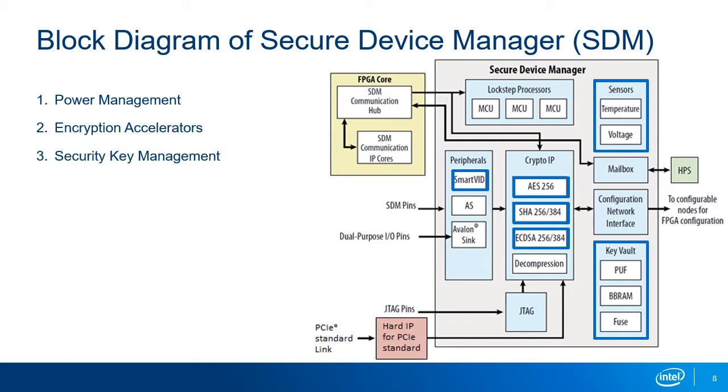The key vault block provides users with volatile and non-volatile cryptographic key storage. Crypto functions, which utilize keys, require the keys to be stored using a special hardware mechanism to mitigate potential side-channel attacks.